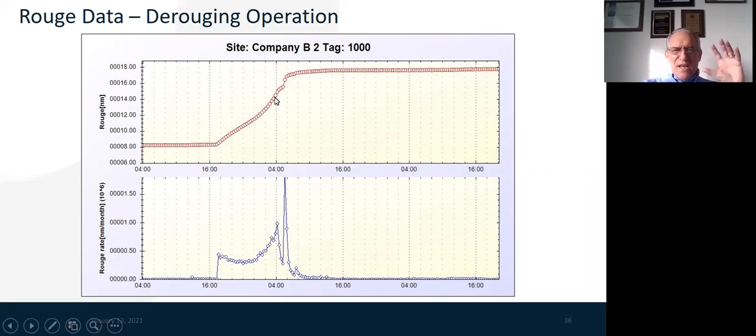Why? Because we're reducing the metal on the piping and the vessels, and that increase in metal shows up in the rouge. The chemistry, again, against the probe, shows exactly what's going on with the metal itself. So after 3 hours, which is a normal practice of most third-party rouge chemical administrations, they say, okay, 3 hours is up, and at 7 o'clock, or 1900 hours, they administered sodium hydroxide.